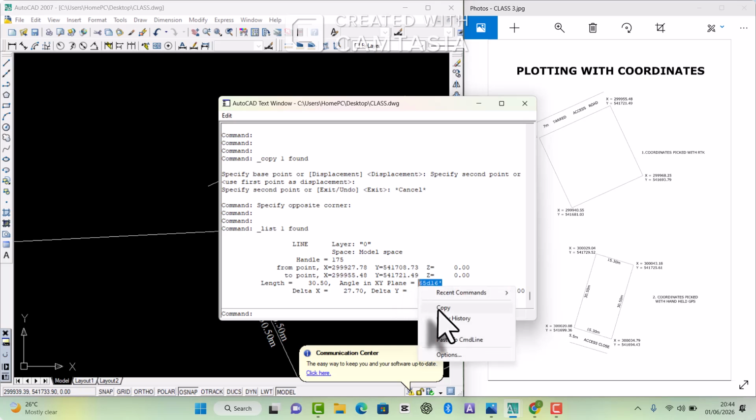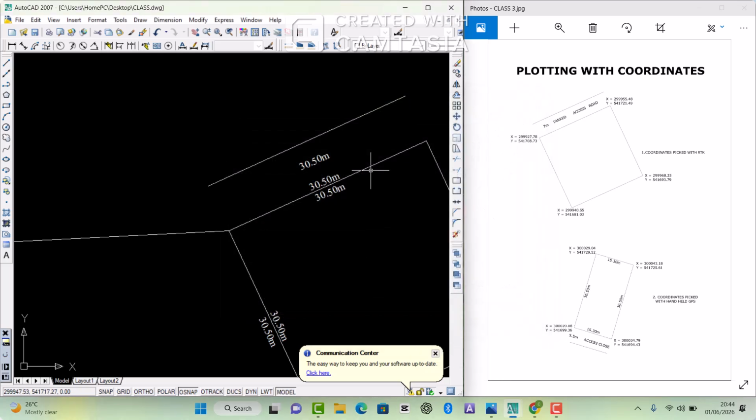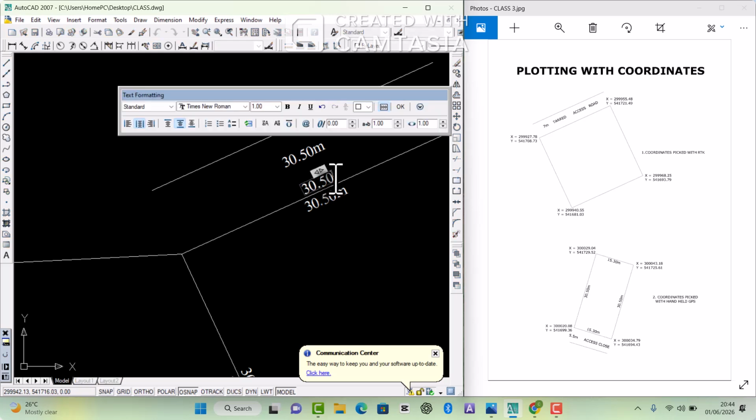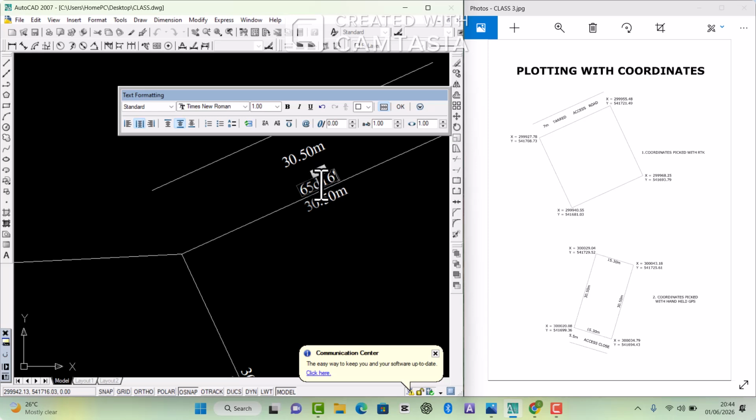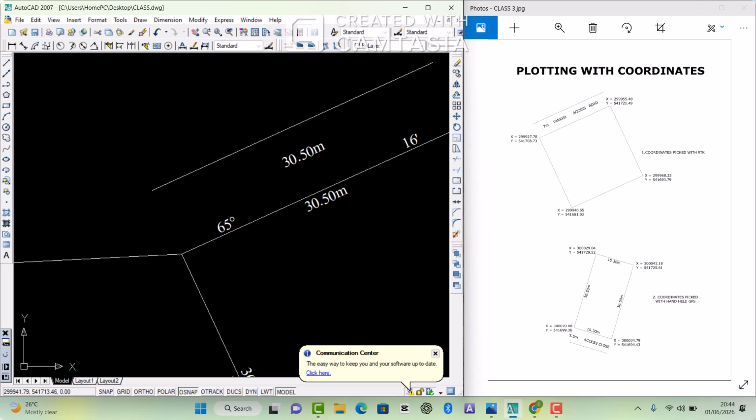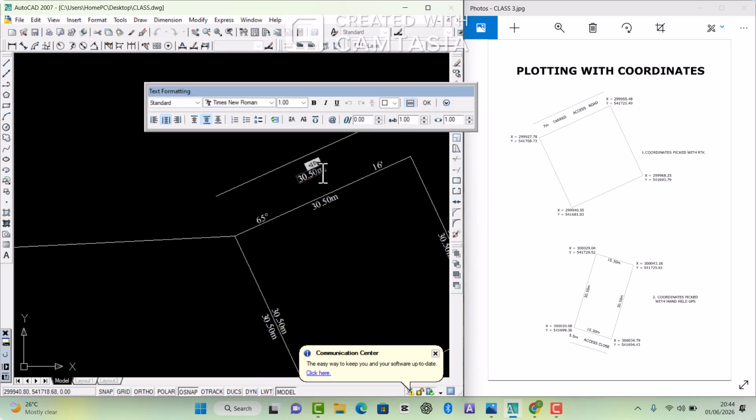You right click, you click copy. You close the box. When you double click here and you backspace, you just right click again and click paste. It will paste what you copied. Now in order to bring out our degree sign, you can backspace that D, hold your shift key and the percentage key, press it twice to come out twice, then you press D. The percentage sign has come out. Then you just space it to convenience. That's all. Here we can edit and indicate our access road.